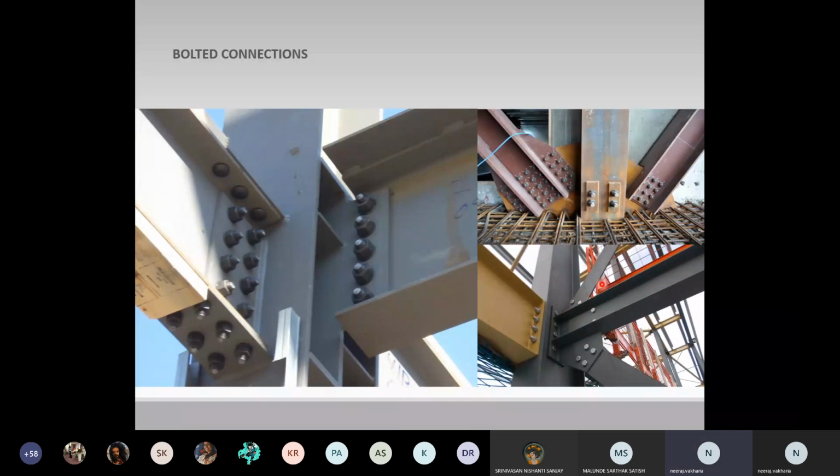A bolt, if you see, is a metal pin, just like the rivet, but with a head formed at one end, and the shank has threads around it, like a screw, so that a nut can be received and the other side can be fixed with the nut. Generally, bolts are used to connect pieces of metal by inserting them through holes in the metal, and at the threaded end, nuts should be tightened. That is generally done by machines, or rather a different kind of driller.